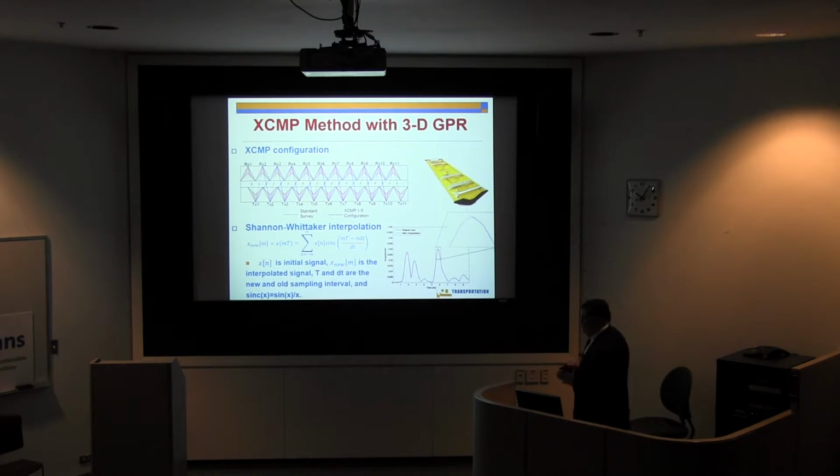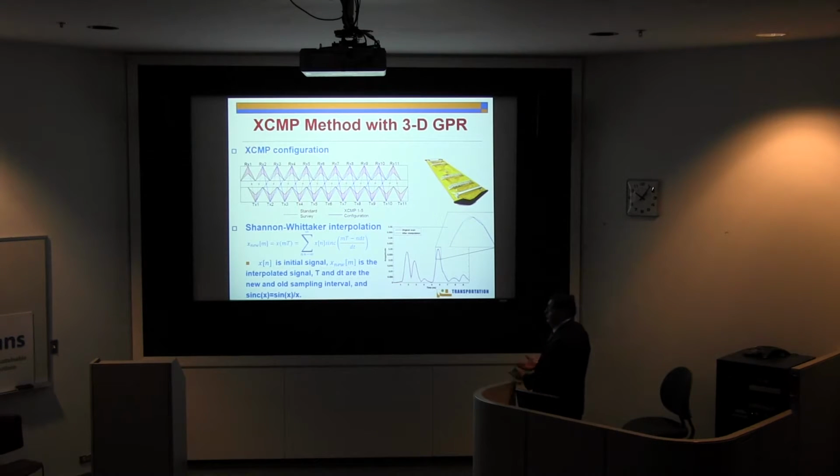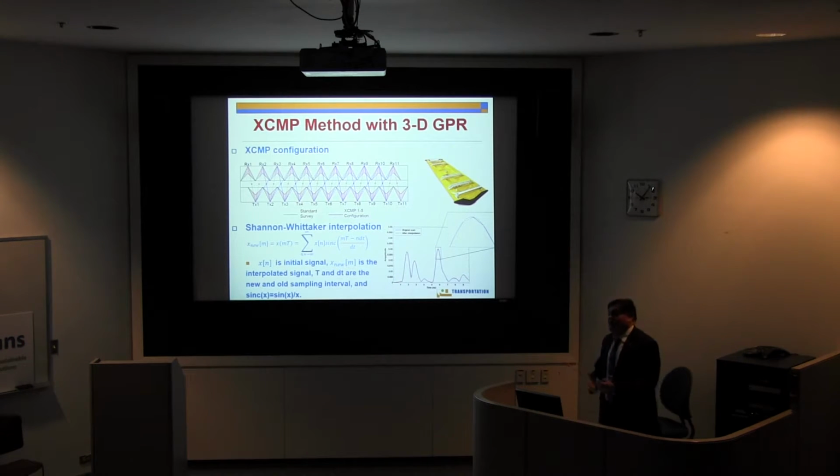The reason why we don't have this kind of big resolution is because of the variations in the frequency, okay? Because when you are getting to 200 megahertz, the lowest, then your wavelength is very big, and then your resolution is going to be less. Again, the higher the frequency, the shorter the wavelength. This means that your resolution is better, but your penetration is less too, okay? So if I have a void in a highway, which happens, at 20 feet, can I use a typical GPR? No, I'm going to be using one in the megahertz. Can I see the voids? Of course, but if it's 1 inch, I will not see it at 20 feet.